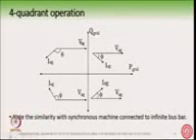Now, therefore, we can see that this voltage source converter can act as a controllable voltage source, and it can place the current with respect to the grid voltage. The grid current can be placed in the 4 quadrants, which is very similar to how a synchronous machine behaves with the infinite bus bar. Basically it all comes from the circuit law, 2 voltage sources connected by an impedance in between, and you can change the power flow.